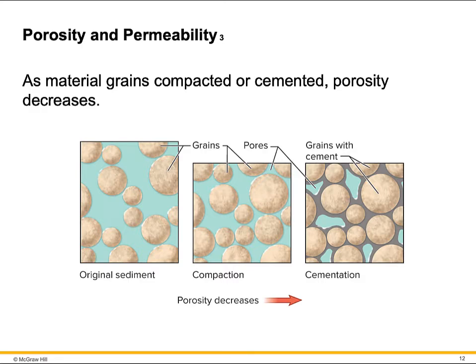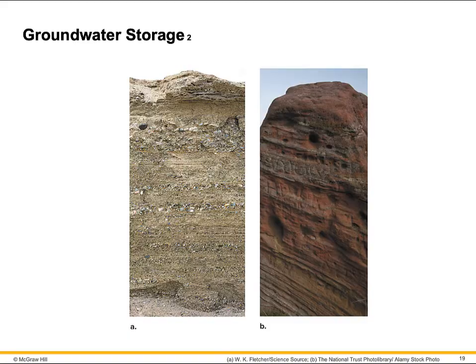The permeability is the capacity of water to flow through earth materials. Water can flow readily through materials with well-connected pore space or many fractures. Connections between pore spaces are wider in coarse-grained material like gravel than fine-grained materials like sand. High permeability does not always go hand in hand with high porosity.